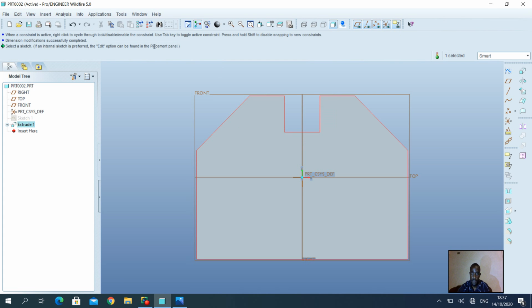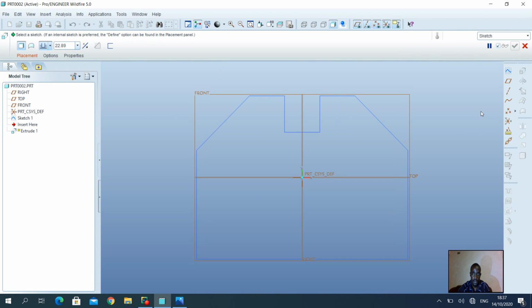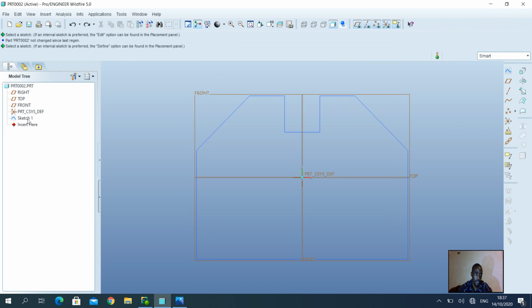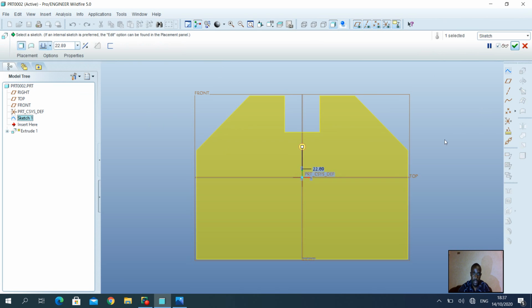Or before I click enter, let me go back to this extrusion slightly. So I'm going to go back to the sketch, and then I'm going to be clicking extrude. There's something that I really want to illustrate here. So I'm going to be selecting this option, extrude on both sides, and put an extrusion distance of 60.